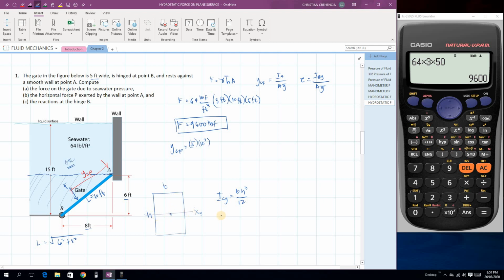Okay. Then, if yung axis of yung moment of inertia natin is about the base, so let's say this is X. Okay. So, yung moment of inertia about x-axis is BH cube over 3. So, paano nangyari yun? So, diba, by transfer formula, so solving for Ix, kung ang alam lang natin is yung CG. So, that is BH cube over 12